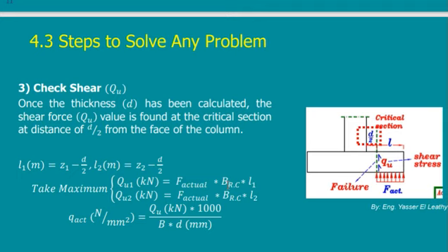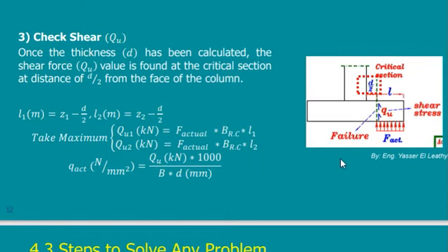So usually I check the shear capacity of the section and compare it to a value. In this case, I'm checking shear. Shear means that I am trying to separate part of the foundation from the whole foundation. Which part of the foundation can I separate? Is it this one at the early start of the footing, or if I go inside,